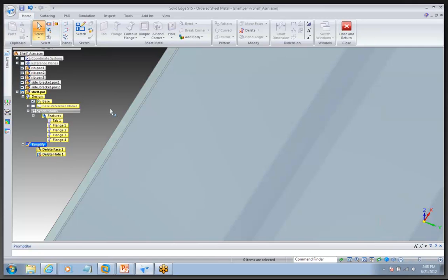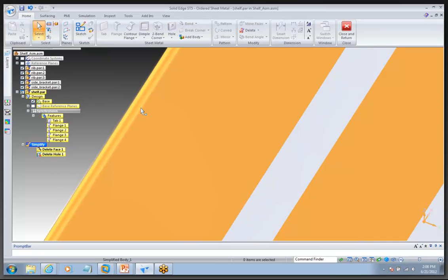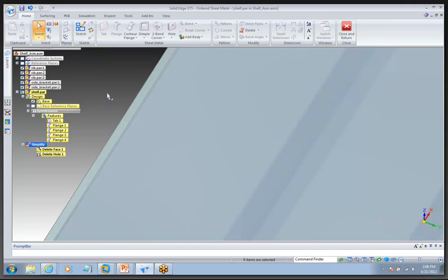And when I was talking about having a lot of elements, it's the same thing going through the thickness here. If I had to use a tetrahedral element, since they have degrees of freedom that are only translational, meaning that it's only x, y, and z displacement, I don't have the rotational degrees of freedom. If I want to capture the bending, I have to get 2 or 3 through the thickness. And you always hear that rule of thumb. You want to have 2 or 3 tetrahedrals through a thickness of some part. Well, if I had to get 2 or 3 and keep the aspect ratio okay through that thickness, I'm going to have very tiny elements. I'm going to have a whole lot of elements driving up my solve time, which is exactly why we have